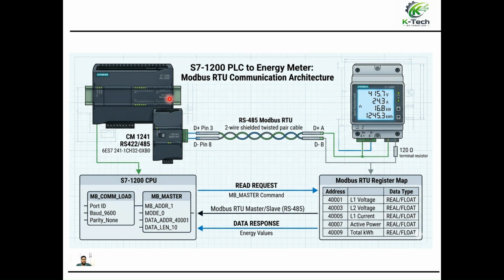So this is my PLC S7-1200, and this is my energy meter, and I need Modbus RTU communication. For Modbus RTU communication, the CM1241 module is required. This CM1241 module supports RS422 and RS485. These are the numbers, and this is the wiring.